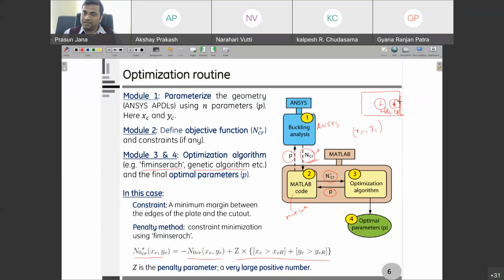And you have to give certain more margin, because in Ansys, if you keep these two the same, there are modeling issues at this location, because you have zero length elements, etc. Then you have meshing difficulties, and you will not find any edge here to give your boundary conditions.